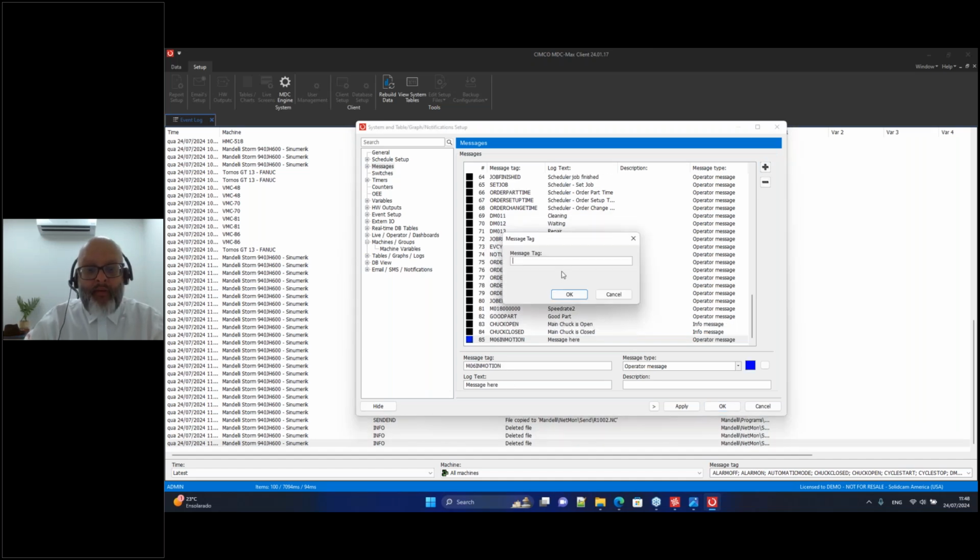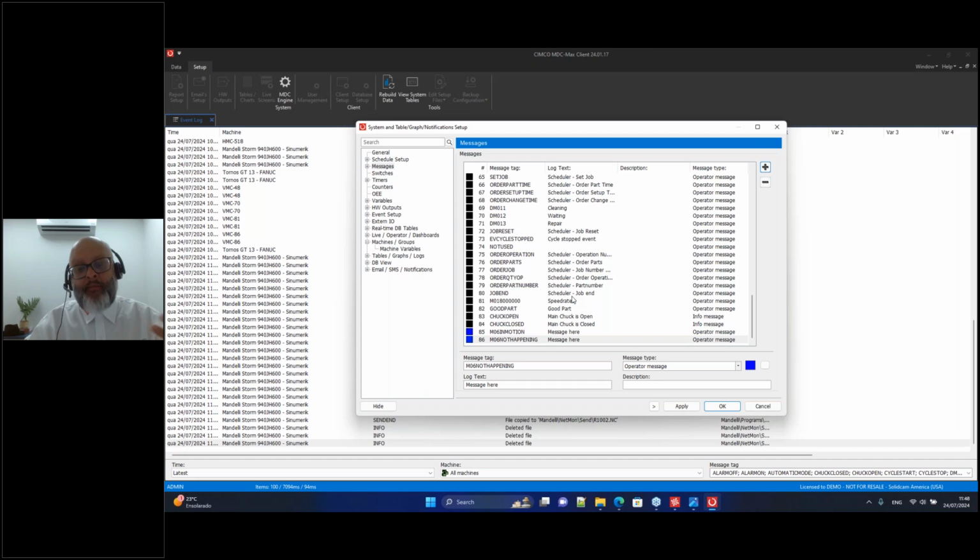And I could add another message and say M06 not happening. Okay, so you create a message, and you can say this is an operator message sent from the CNC control, or it's just a message that we get from the PLC, or it's an error message, whatever. So I'm gonna click apply.